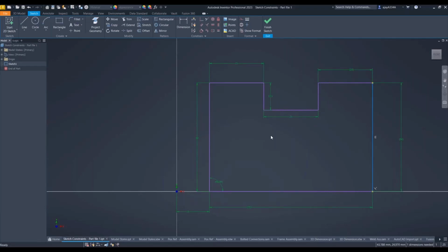So that's essentially where it is. If you pull the drawing, you can see that it's moving around. So this is where we would need to constrain. If we press undo there, and we look at, there we go. Now we see that the length of this line is given here, and the top of this line to the origin point is also at 50 millimeters as given here.